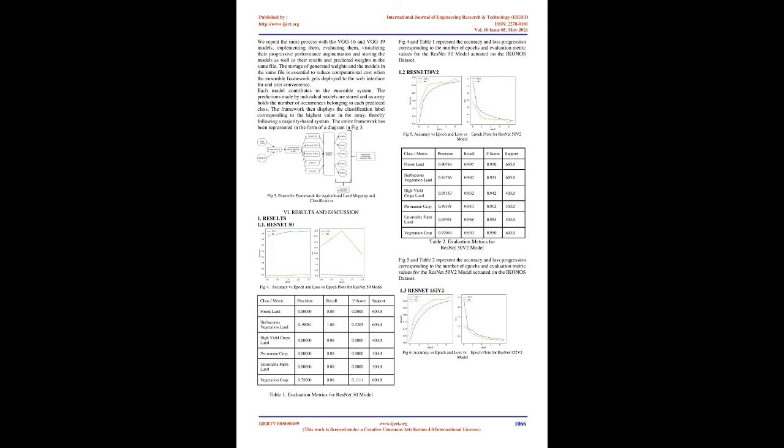[12] proposes a deep CNN architecture which has an input layer, 5 convolutional layers and 5 successive fully connected layers, which automatically classifies outdoor laser mobile survey information. The architecture uses the spatial pyramid, SP, concept during voxelization of MLS samples to overcome the problem of several points within a voxel assigned to high point density. This model was tested on 5 variable combinations of classes consisting of tree, non-tree and electric pole classes from the dataset.